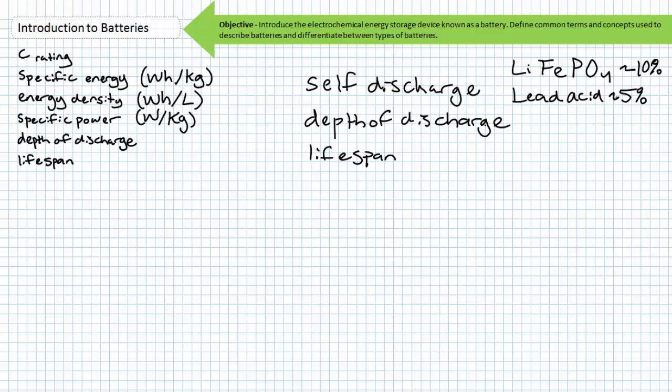The internal chemistry of a battery also dictates its response to charge. A lithium iron phosphate battery might take only an hour to reach full capacity, whereas a lead-acid battery might take 8. A lithium iron phosphate battery, however, essentially cannot be charged at sub-zero temperatures without a heater, whereas a lead-acid battery can, although at a reduced rate. This again suggests that no one battery and no one chemistry does it all.